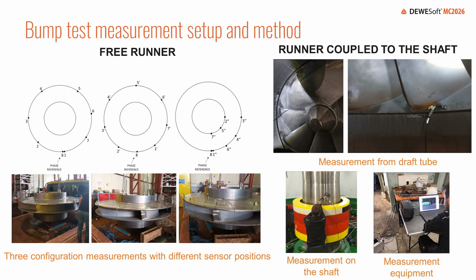A few months later, when the runner was coupled to the shaft, we repeated the measurement. This is from the draft tube, and we also put some accelerometers directly on the shaft above the turbine, and you can see me hitting the shaft with a rubber hammer. And here is the Dewesoft equipment which we used for the measurement and analysis.